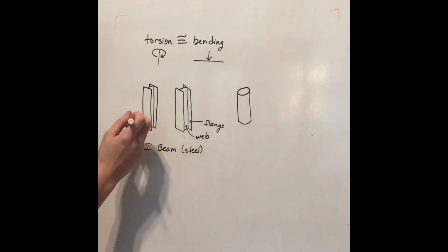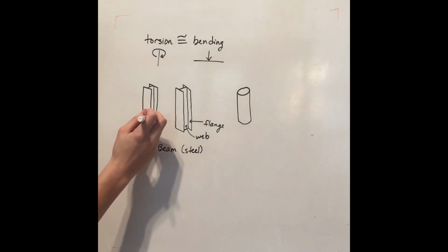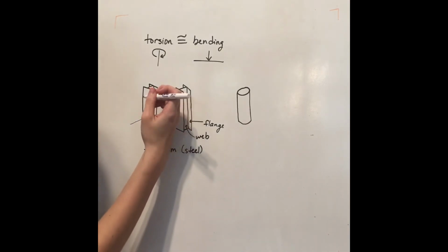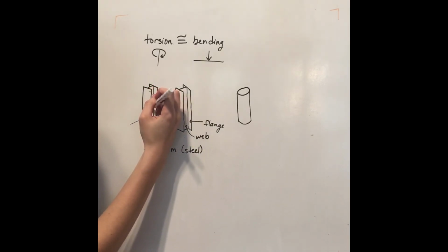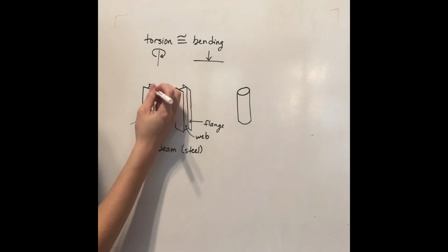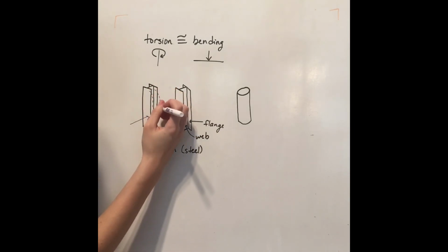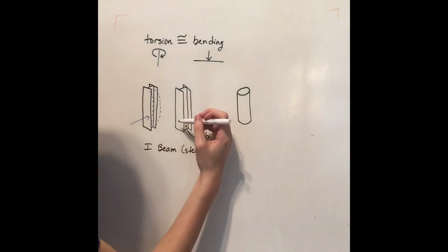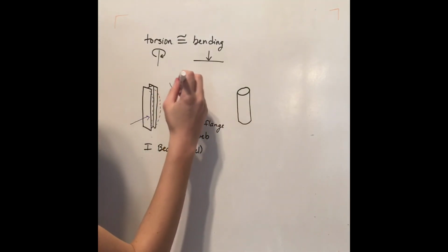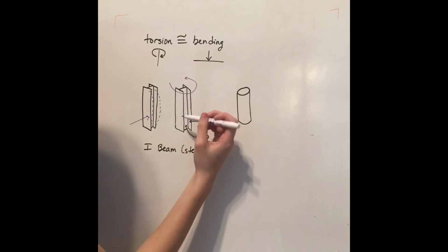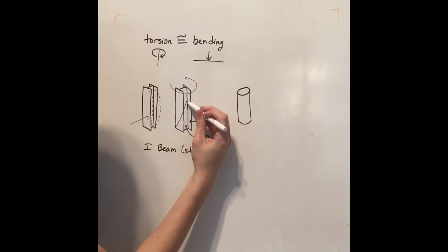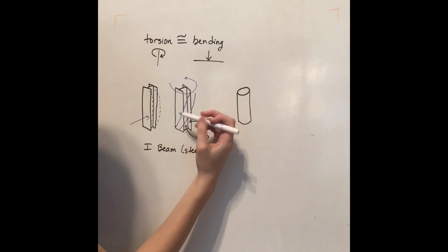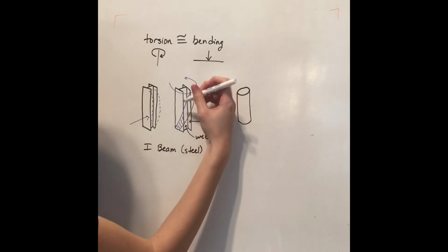The shape of an object that undergoes torsion also has a great effect on whether or not the object will resist the stress. For example, an I-beam's unique shape allows it to resist bending force easily because the web prevents the 2 flanges from stretching too far on the bottom and becoming too compressed on the top. However, when an I-beam undergoes torsion, nothing stops the web and flanges from being twisted around the axis of rotation, so the shape is not ideal for handling torsion stress.